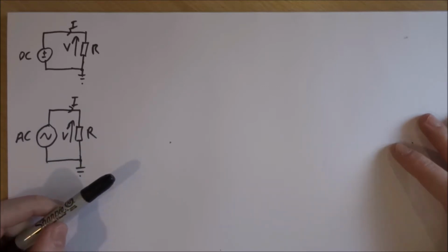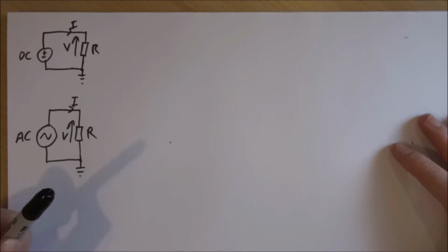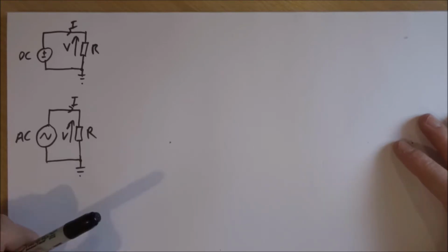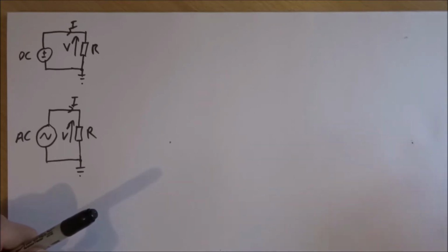The RMS is used to quantify the amount of voltage or current needed to supply an equal amount of energy to a load in a given time, regardless of whether it's an AC waveform or a DC waveform. This basically means that an RMS AC voltage will deliver the same energy to a load as a DC voltage over a given time period. If the time period is variable, then it means that the average power delivered to the load over that time period is equal, be it an AC supply or a DC supply.